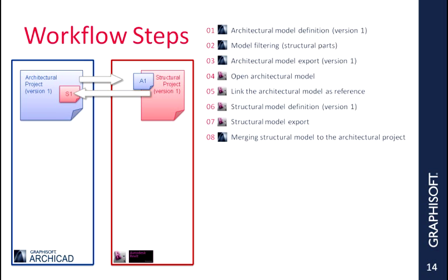By default, the new imported elements are protected according to the reference model concept. Architects may compare two view sets. One contains the architectural model, and the other contains the imported structural model. They can use the Trace and Reference tool to aid the comparison of the floor plan and section views. Architects can query the profiles and materials decided on by the engineers.